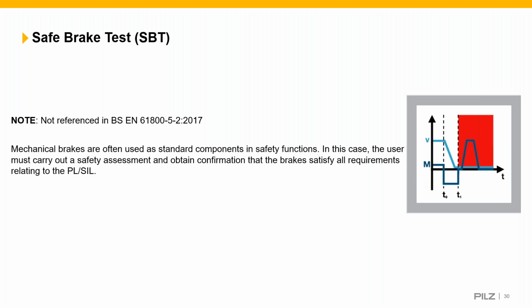So the safe brake test checks the function of the brake. The brake test basically should be carried out again based on risk assessment. This can be every shift, so every 8 hours, for example, or after each production cycle, but just depending on the hazard that's actually presented by that suspended load, for example. So it's down to risk assessment as to how often that should take place. But something that should certainly be considered due to the fact that you'll have parts that wear over time. And then of course, if eventually it does fail, and it may possibly fail in an unsafe manner in this case, then it could cause quite a lengthy downtime, which can be easily avoided if the brake test is implemented.